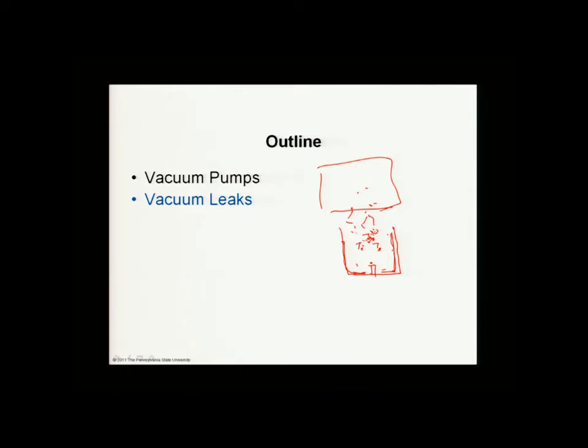It operates at essentially room temperature, but you do have to worry about the coating here and what you have trapped in the coating, and perhaps recoating this to make sure that it doesn't become a source of outgassing and molecules working back into the ultra-high vacuum region. So you do have to control in particular the walls inside here, to make sure they don't become a source for outgassing and molecules coming back. But it's a very simple pump, very, very good pump for pumping oxygen.